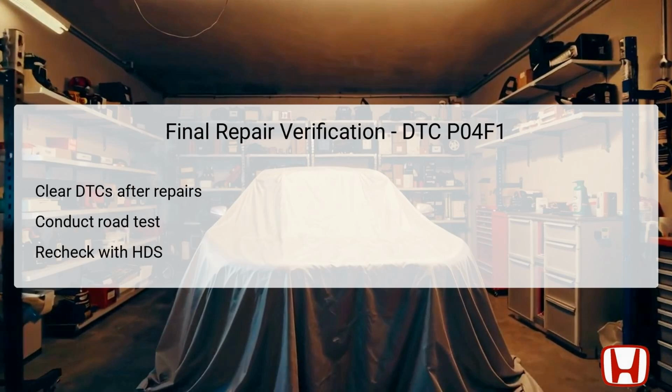After completing the troubleshooting and necessary repairs for DTC P04F1, it is imperative to perform a final verification to ensure that the problem has been resolved effectively. Begin by clearing any diagnostic trouble codes, DTCs, present in the system using the HDS. A road test should follow to confirm that the vehicle operates without triggering the check engine light and that it meets emission standards. Post-road test, recheck the vehicle using the HDS to verify that no new DTCs have appeared and to ensure that no pending DTCs remain.